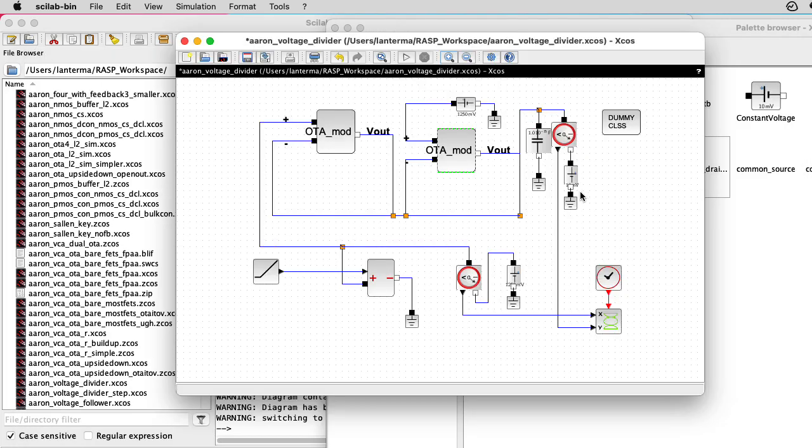Beautiful. So I found this capacitor trick to be incredibly helpful. Basically, all of the simulations that I've been trying for the past couple of weeks that I haven't shown you because they weren't working, I can now show you in future videos because this capacitor trick fixes the problem. Again, just a very tiny little capacitance here makes the simulator happy.